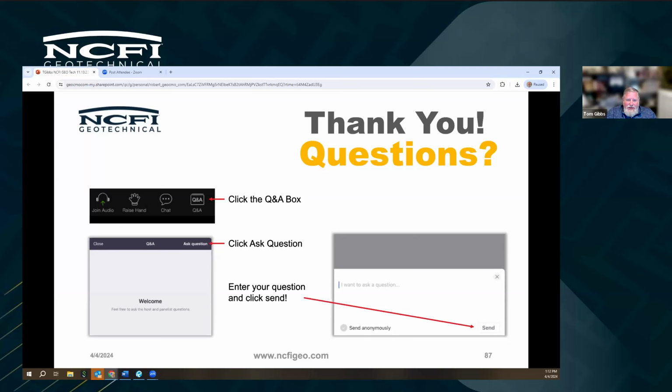So PEX is a good delivery method if you're looking for something that's a little more flexible than metal. Obviously, metal is easier to drive into the ground, but if you're, for instance, doing say pipe abandonment or something, PEX works really well. And the packer system or injector system that we use can be used with PEX. Shoot me an email if you've got any questions about how to do that.